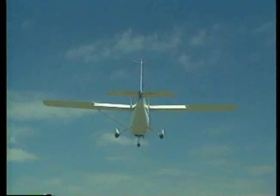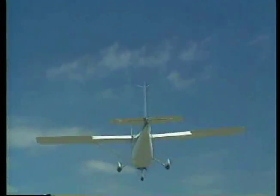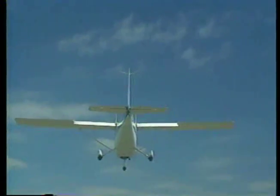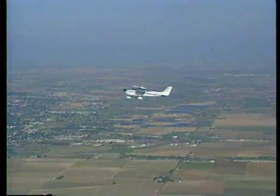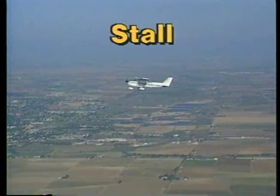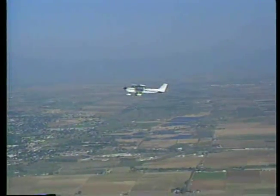During this time, you still have full control of the airplane, meaning you can still maintain attitude, heading, and altitude. This stage of flight is sometimes called the incipient stage of a stall, or an imminent stall. If recovery is not made at this point, a stall occurs. In a stall, the wings no longer sustain the lift necessary to maintain flight. Once the critical angle of attack is exceeded, the nose will pitch downward.